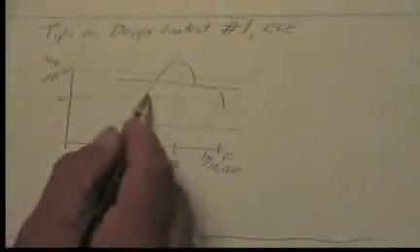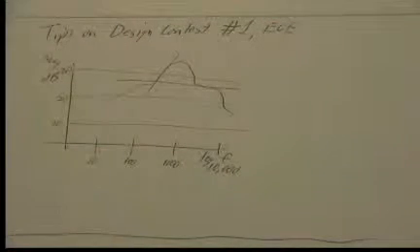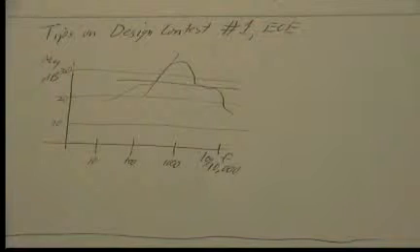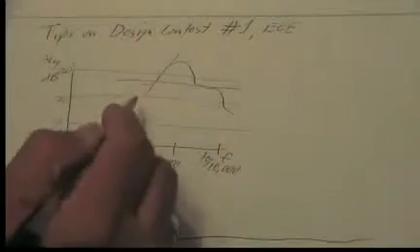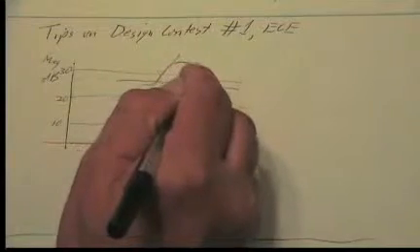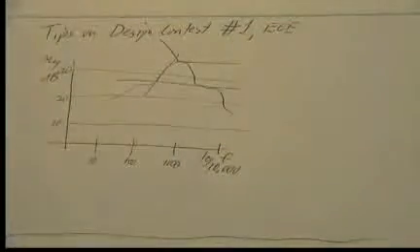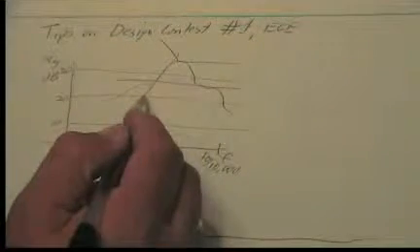approximate it as a straight line. I could say, well, what's the slope of this line? And I'm looking for some sort of slope in terms of, for instance, decibels per decade, like between 100 and 1,000, roughly speaking. What is the slope of that thing? And what I want to do is apply a filter that's going to cancel out that decline. And so basically I'd be trying to produce a filter, let's say for this particular case, a filter that would start rising at a point in frequency that will basically cancel out the fall.